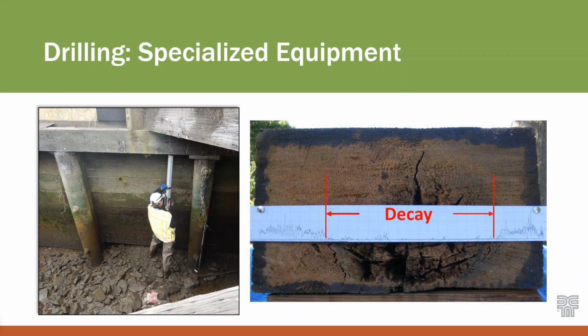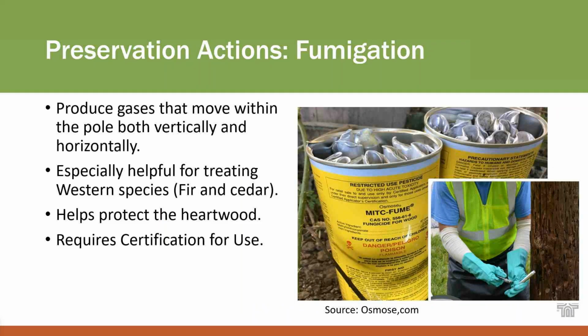The holes that are made from it are so tiny that they're considered a non-destructive method. They make a bunch of different varieties of those. There are super fancy ones that have Bluetooth and report the readings back to a tablet. There are ones that sketch this out on paper, which is what's shown in this picture on the right. Then they have manual ones with a feed tube, which I didn't get into in this presentation, that are basically handheld, and you feel it and look at a gauge as it goes through. There are different options for seeing where that rot is.